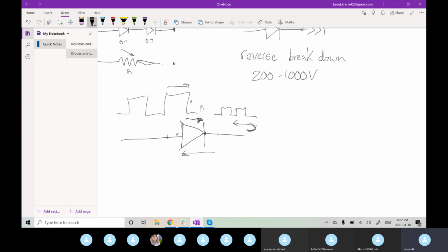So although it will get rid of this bounce back noise, you lose your top end. Instead of having a clean 5 volt to 0 volt, it'll become a 4.3 to 0 volt signal. But it would be able to stop any bounce back interference. Okay.